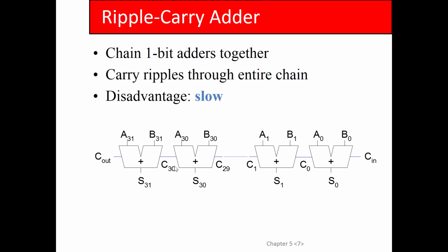It's like saying, when you do decimal, like if I'm adding two numbers, 199 plus 120x, I don't even care what that digit is. I know that based on those two digits alone, I'm going to have a carry into this row. Now it's decimal, so I don't know what the carry is going to be. But since this is binary, my carry can only be 1 or 0. So generate means I generate a carry.